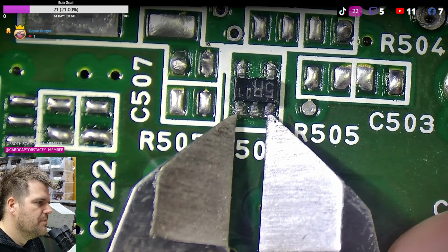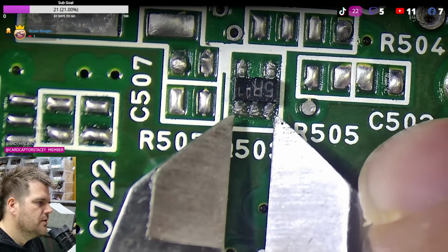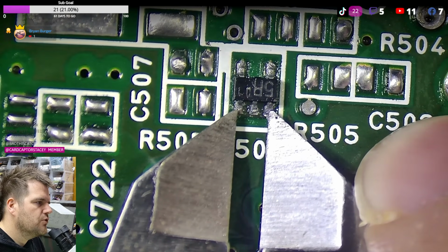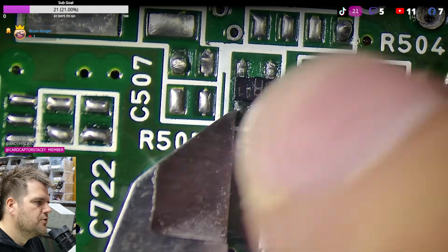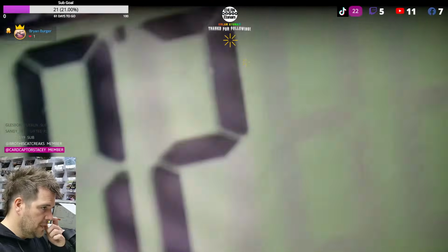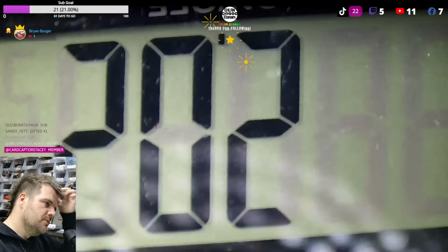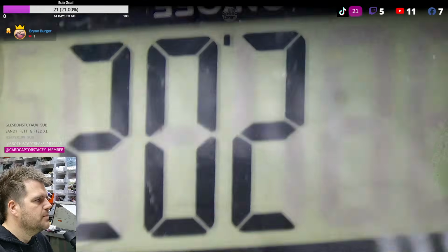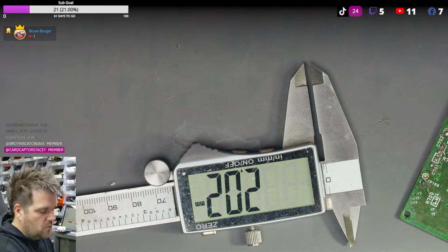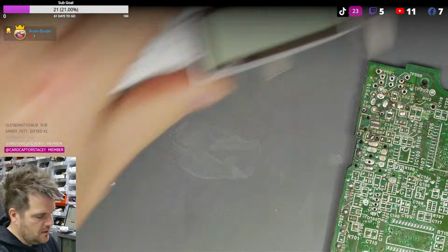So that's now center of that pin. And then I'm trying to move this one so the width opens and basically both tips fall central. And that now means we've got 2 pins in there, 2 gaps. So 1, 2. This means this needs to be divided by 2. And you can see, if we zoom out a little bit, we're exactly 2mm. So that's going to be a 1mm pitch. There's a 1mm gap between the pins.